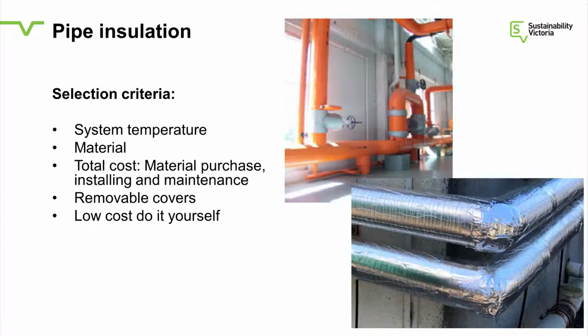The other thing that I like too is what I call low-cost insulation. So you can clad all the pipes and you can put flexible things on the high-pressure, high-value things. But in a lot of condensate lines or chill water lines, not so much for gas but for power, a lot of people don't insulate the small, lower temperature systems, but they still waste a lot of energy. The reason they don't do that is because of the cost. To get cladders in, it's quite expensive. It's not core, they've done their main steam lines, but they just can't afford to insulate all the condensate lines and other things.